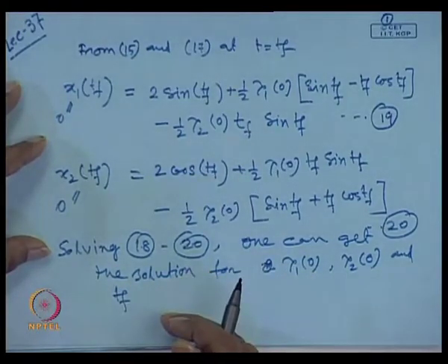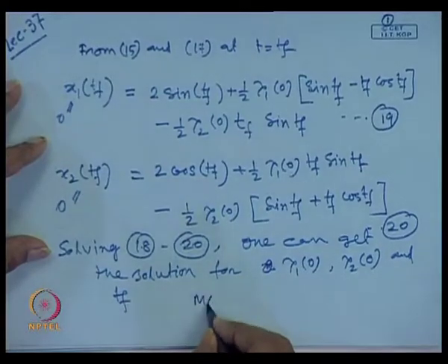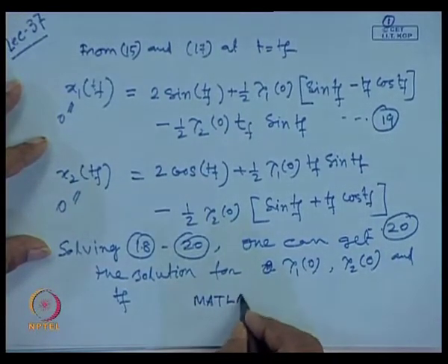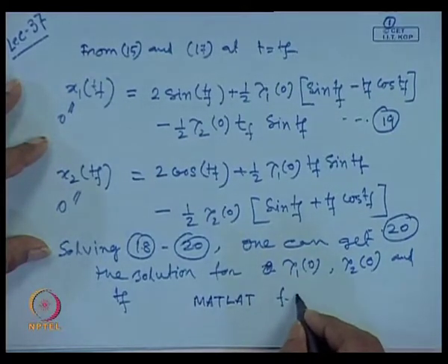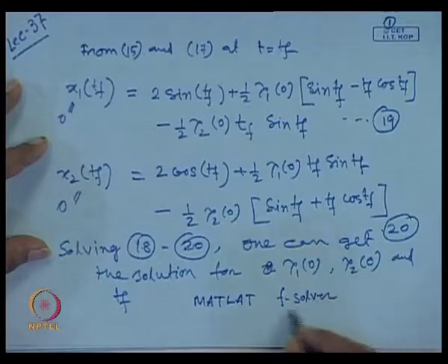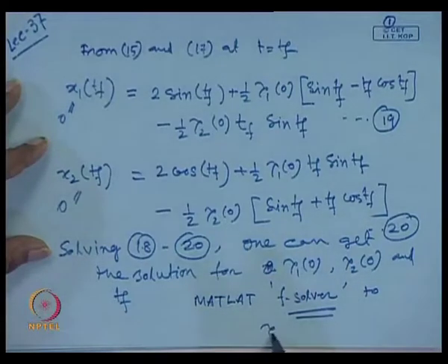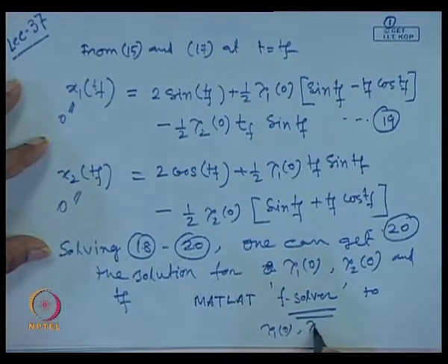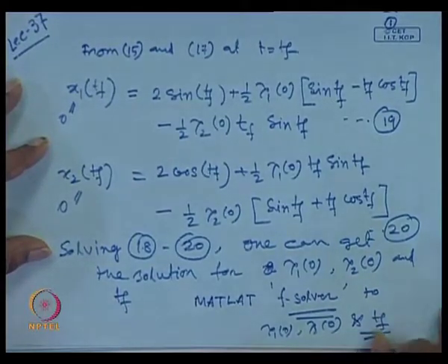You can use the MATLAB toolbox, where there is a solver, fsolve, to get these three unknown values, lambda1(0), lambda2(0) and t_f. We can solve this.